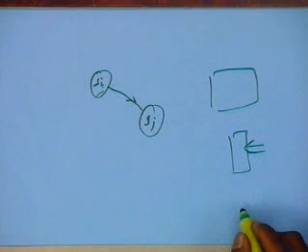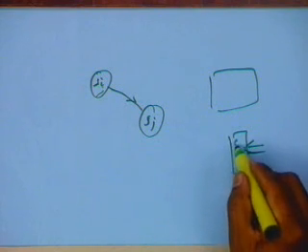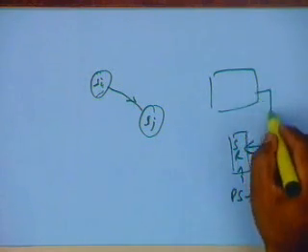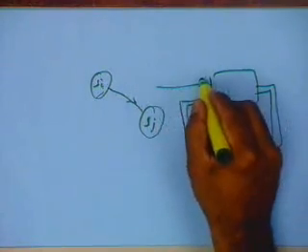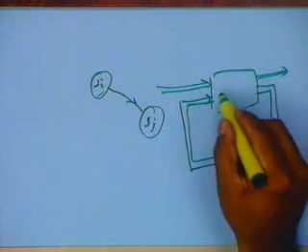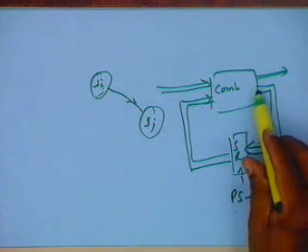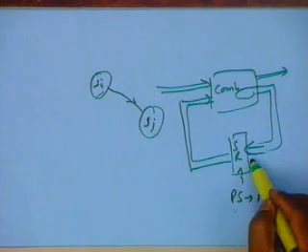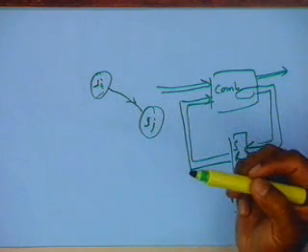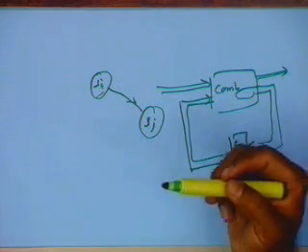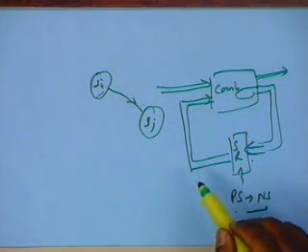If you look at the input of your state register, you go from the present state to the next state. This is what the state register does. Take the output, a Mealy model of a machine. This is your combinational logic. So if you are going from present state to next state, the logic that generates these transitions is going to generate fewer transitions if I am coding them close to each other in terms of the binary coding. So it has also an influence on this. Of course, this is just one factor, but these are the factors when you talk of coding of states and instructions.